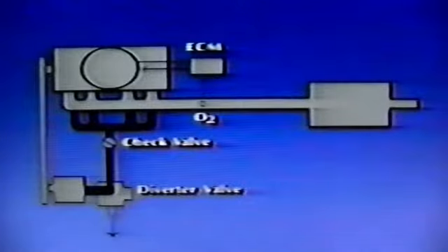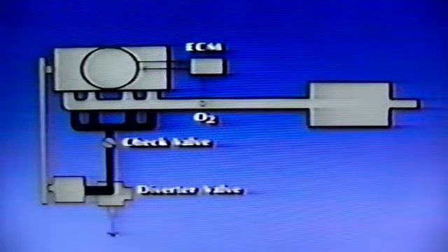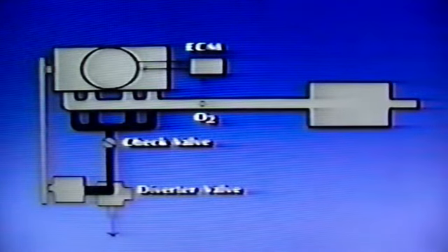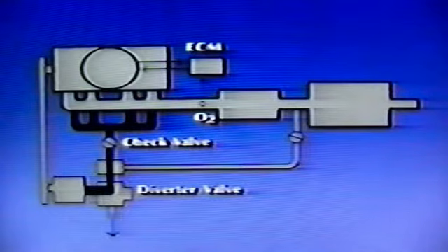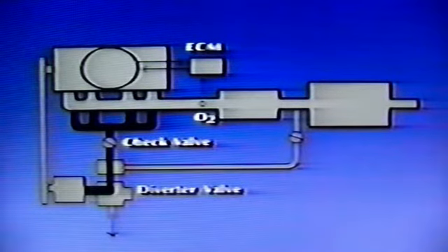exist. Consequently, in closed loop, it is imperative that we get the air out of the exhaust manifold and through the air cleaner. In a 2-hose system, this is accomplished by an electrical signal from the computer to a diverter valve. In a 3-hose system, we stop sending air to the manifold and switch it downstream to increase the efficiency of the oxidizing bed of the catalytic converter. This gets us well past the oxygen sensor and eliminates the possibility of false signals.